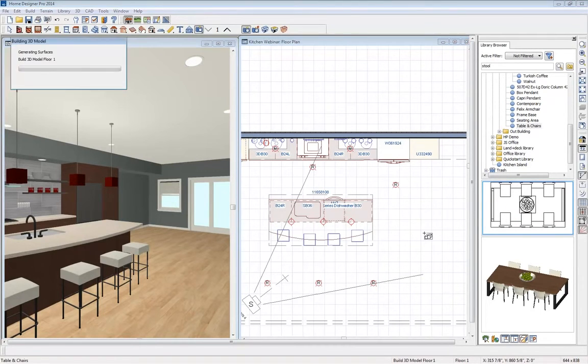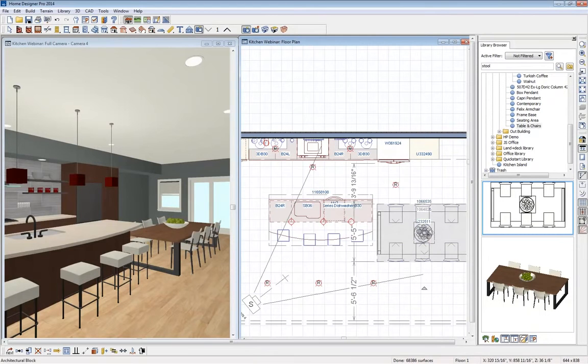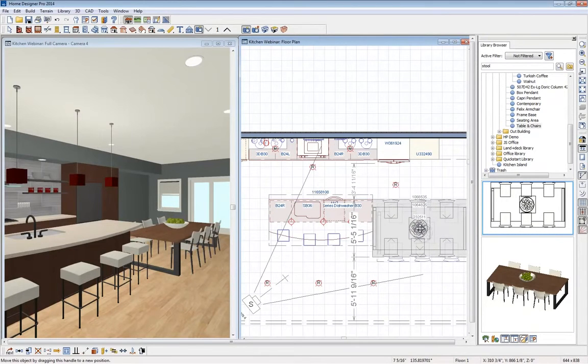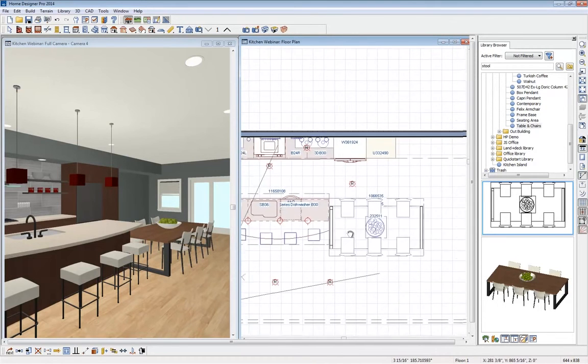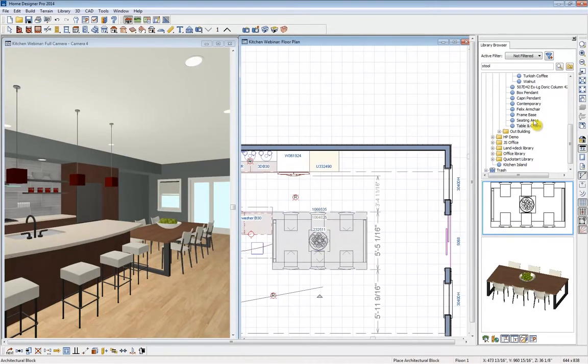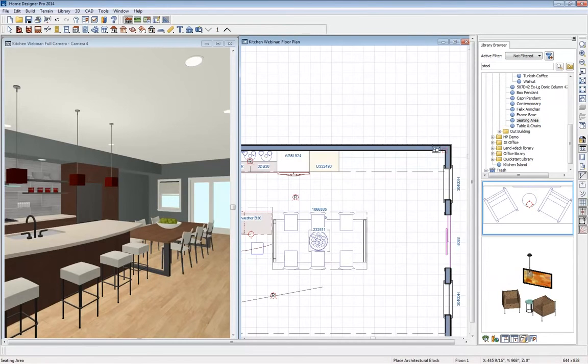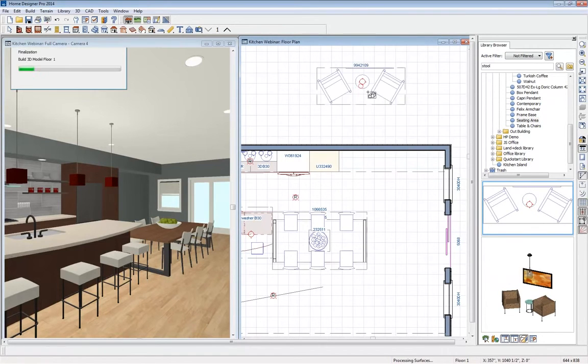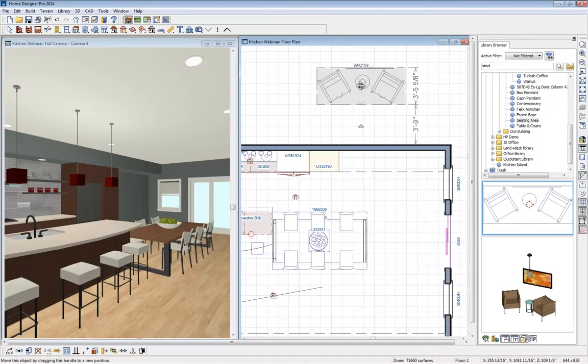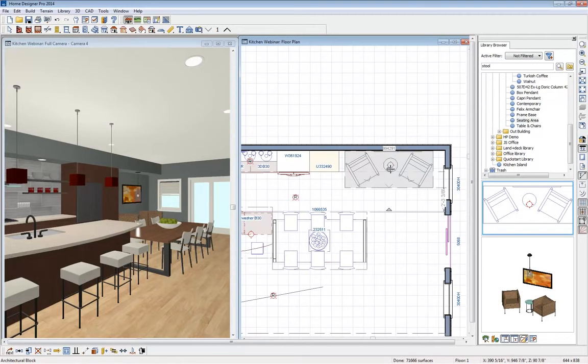And just kind of drop them randomly in here, and then let's move those over. And then I would like a seating area. So this seating area, I'm just going to click outside of my design because it's kind of large, and then use my control key, just hold that down to free up the snaps and drag it right in.